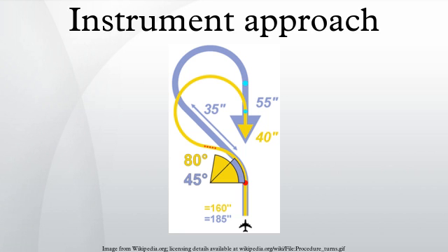It is very common for a circle-to-land maneuver to be executed during a straight-in approach to a different runway, for example, an ILS approach to one runway, followed by low-altitude pattern flying, ending in a landing on another runway. This way, approach procedures to one runway can be used to land on any runway at the airport, as the other runways might lack instrument procedures or their approaches cannot be used for other reasons.